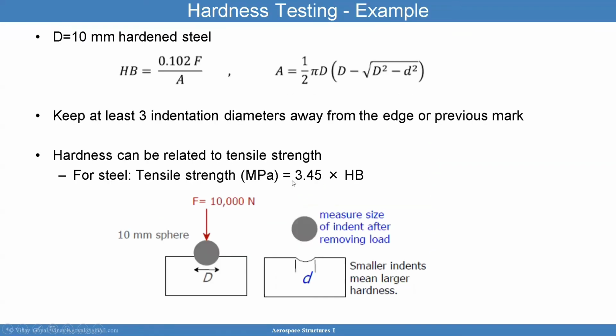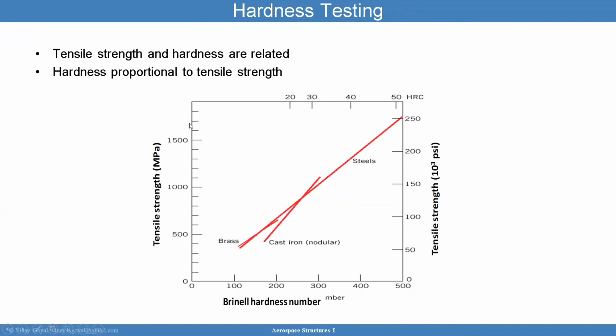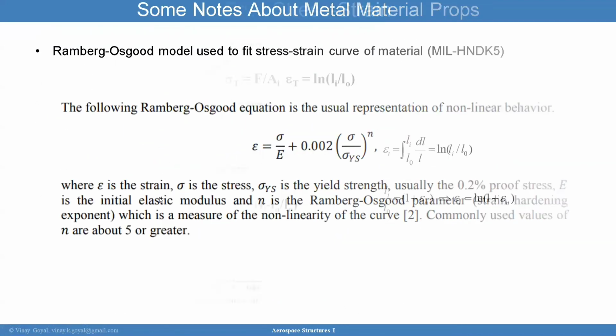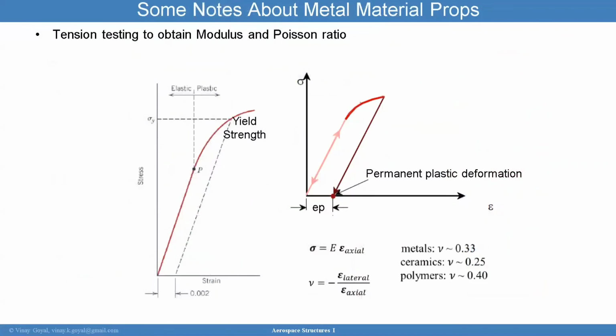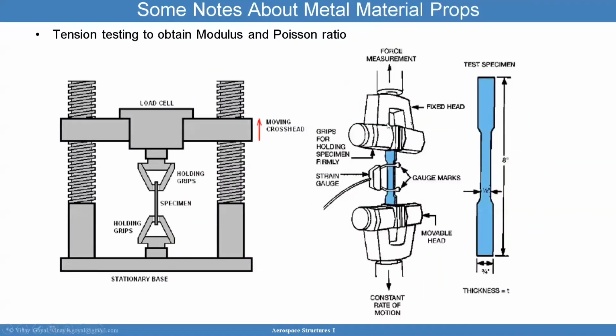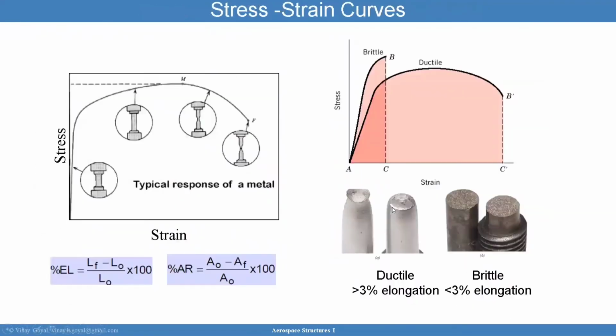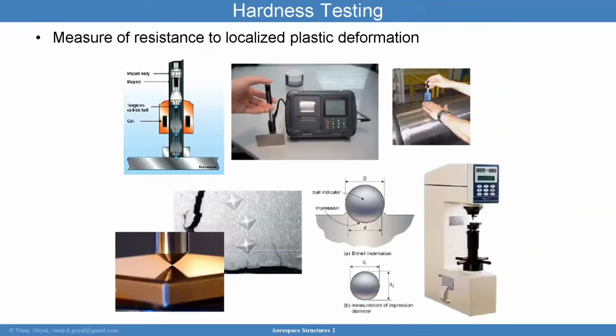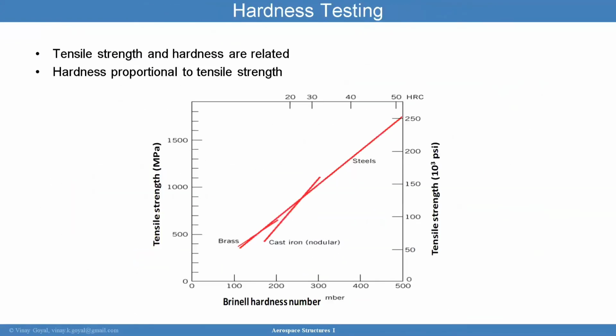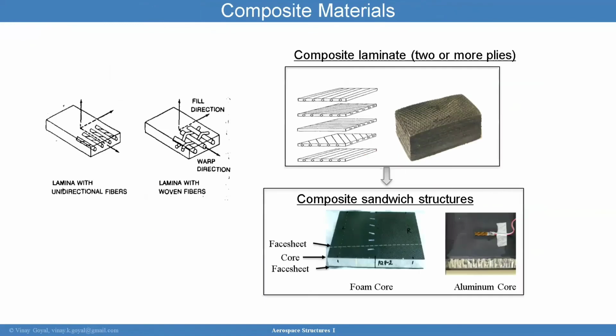But the important thing is you can use a Brinell test, and basically the Brinell hardness number can be correlated to tensile strength. So not only can you measure the strength through a test like this, through this machine by applying a tension load, but you can also measure it by performing indentations into the material, which is quite exciting to see, and it can be used in forensics.